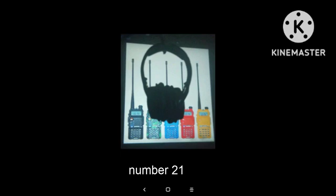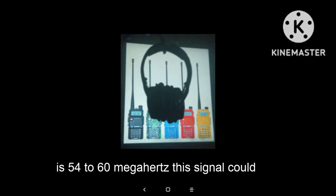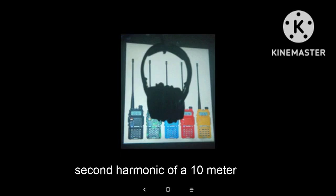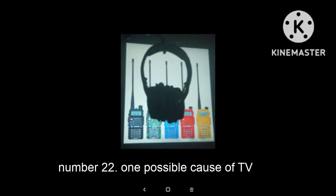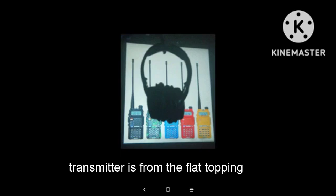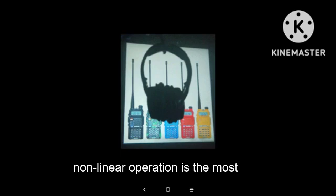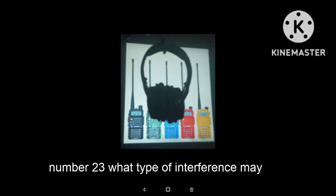Number 21. An interfering signal from a transmitter is found to have frequency of 57 MHz. TV channel 2 is 54 to 60 MHz. This signal could be second harmonic of a 10-meter transmission. Number 22. One possible cause of TV interference by harmonics by an SSB transmitter is flat topping. Driving the final amplifier into a nonlinear operation. The most appropriate remedy for this is reduce microphone gain.